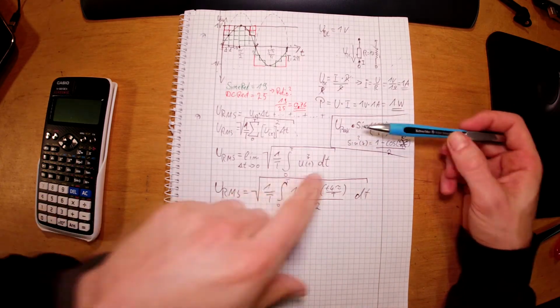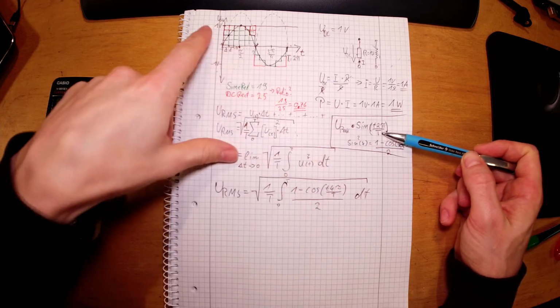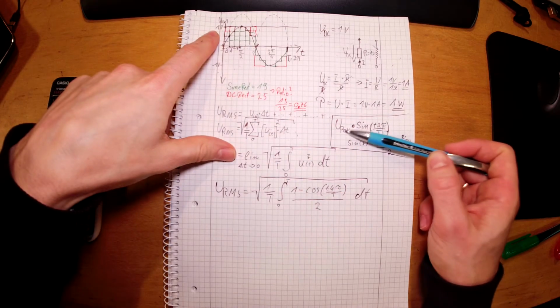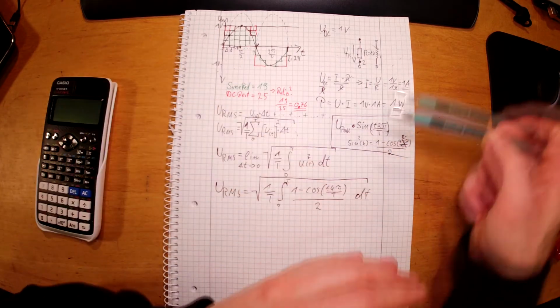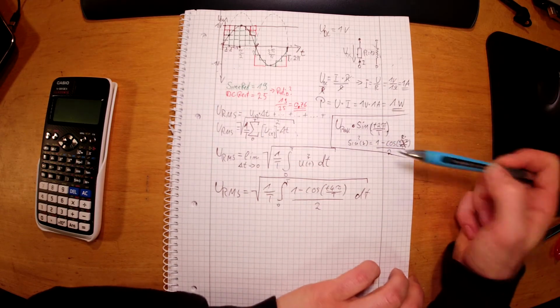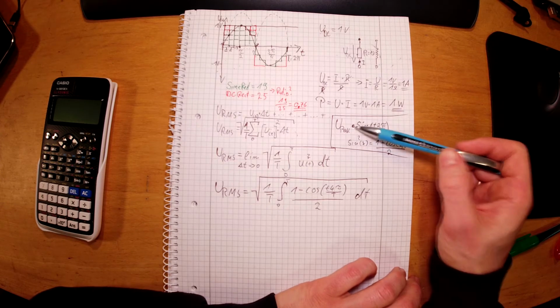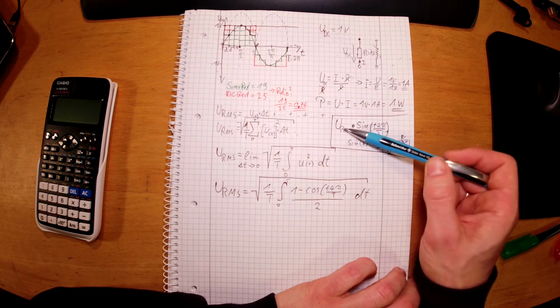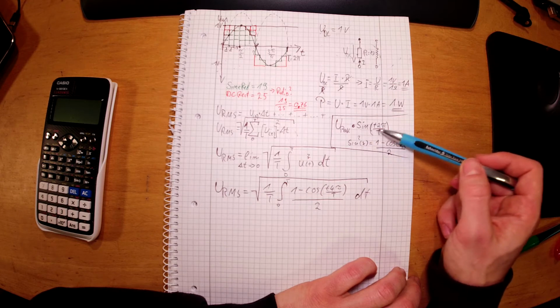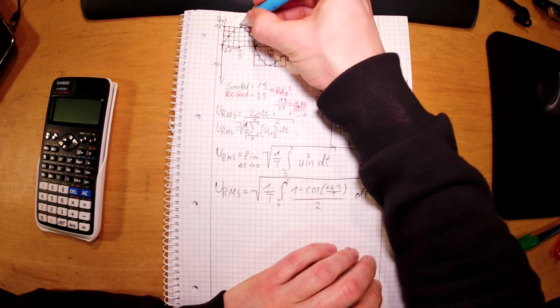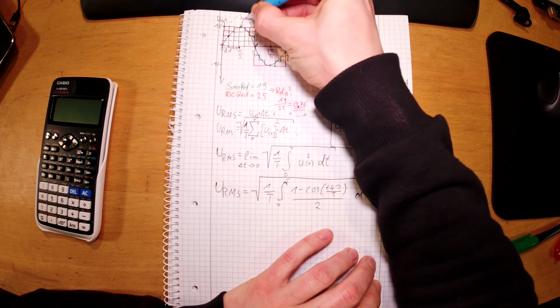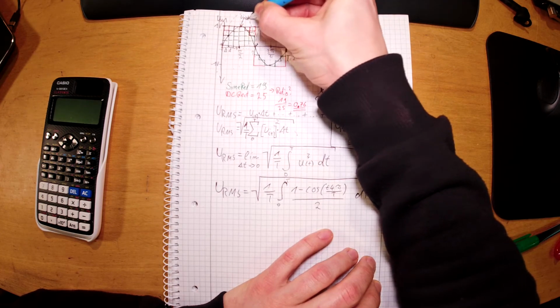You will understand it when we do not have a value that is 1 volt, but another value. We have to multiply it with the maximum value that our sine wave is reaching at the top, because the sine wave is delivering maximum 1 volt if we don't do it. If we don't have that factor for other voltages than 1, we will not get the exact peak voltage on this point. U peak. Okay?